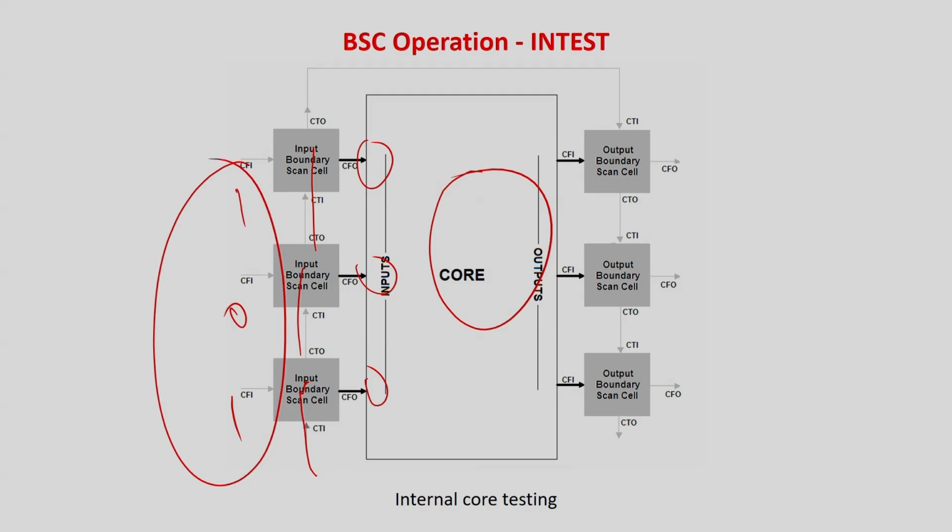EXTEST he will not tell anything. EXTEST is my responsibility because I am applying something. EXTEST is simple, I just have to test the interconnects, because if I know that the cores are operating fine by the patterns the core vendor will give me, then it only remains that I have to test whether the internal lines are operating properly or not. Maybe I can do some kind of overall system functionality test, that is also possible, but that does not generally come under the P1500 standard.